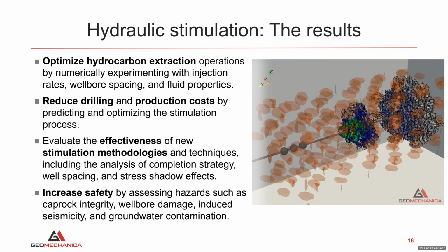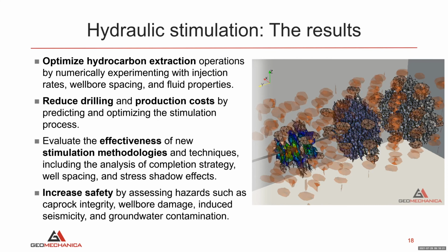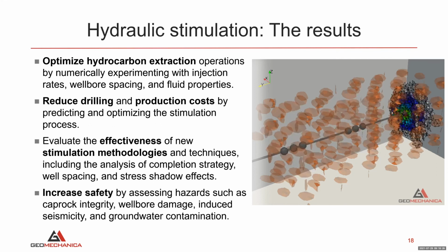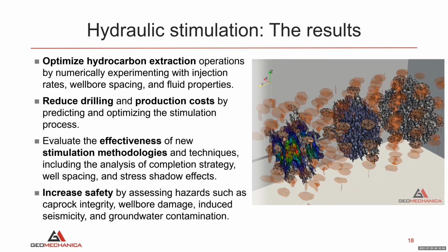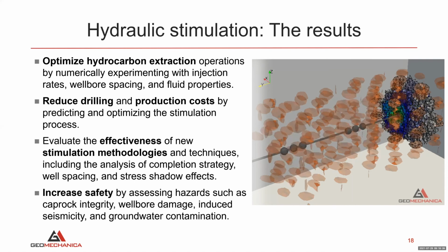And finally, you could increase safety by assessing hazards such as caprock integrity, wellbore damage, induced seismicity, and groundwater contamination. On the right-hand side, you're seeing an animation of a 3-stage injection, and that is also tapping into natural discontinuities. And this simulation is capturing stress shadow effects and the effect of multiple injections in the same cluster.